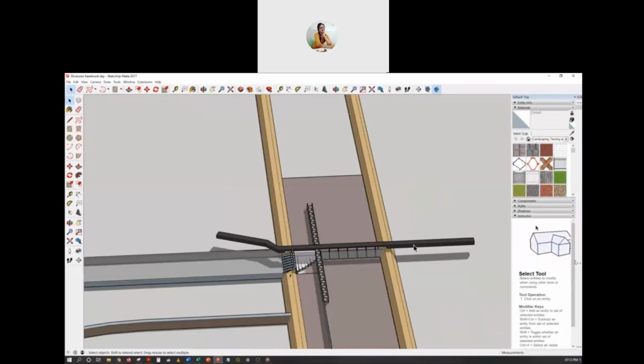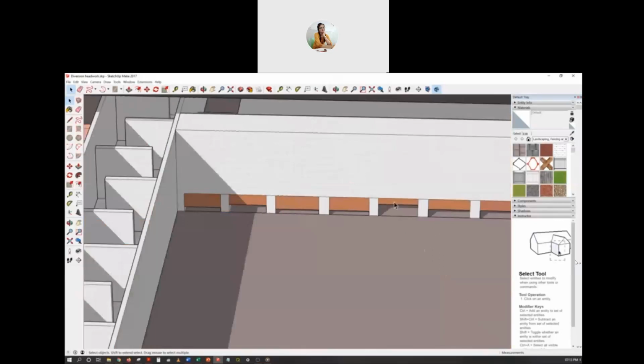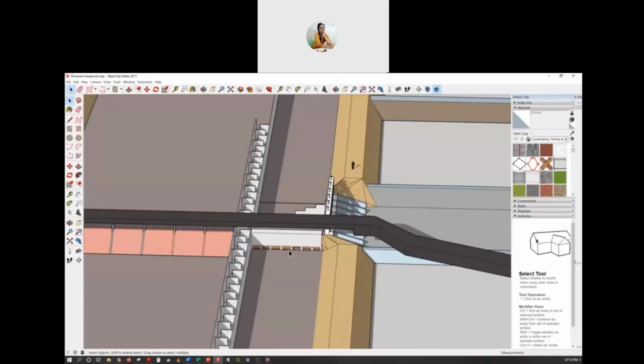Now, there is something else called an undersluice gate. These undersluices are, again, gates. These gates are opened or closed based on need, so that water from the upstream can be released to the downstream. Generally, they are not all closed completely. Only a few of the gates are closed, or they are partially opened, so that a controlled amount of water is released to the downstream.